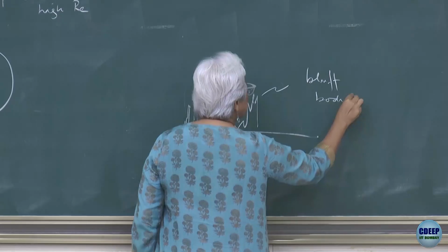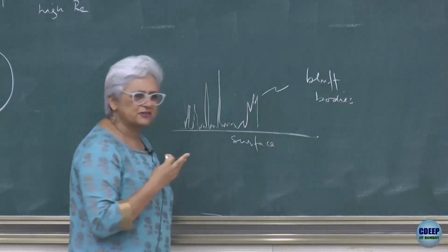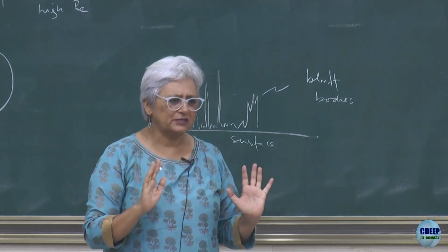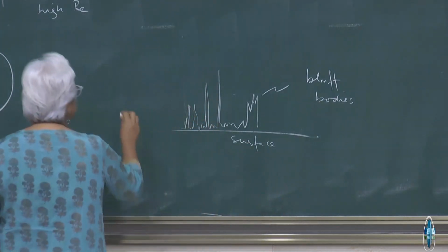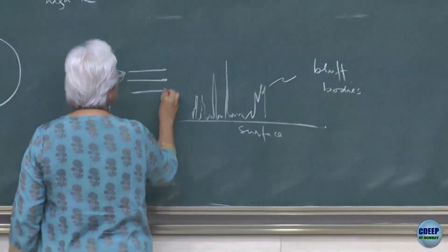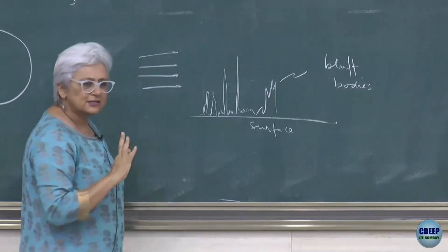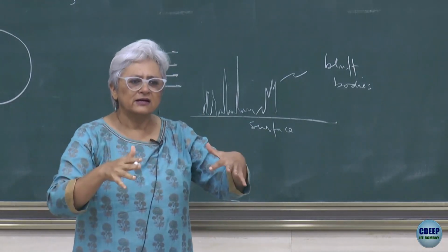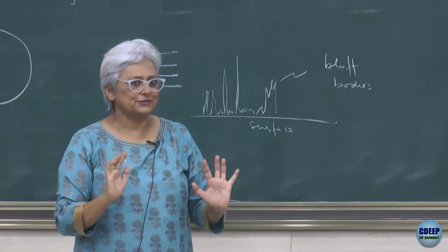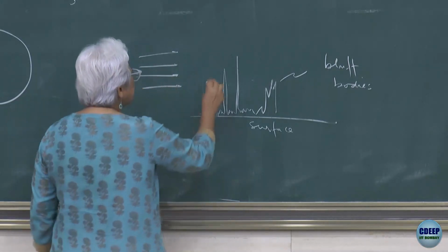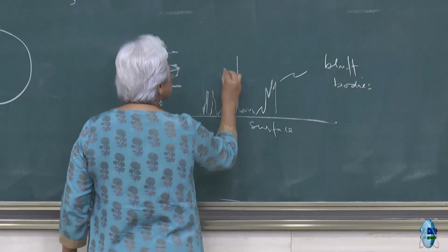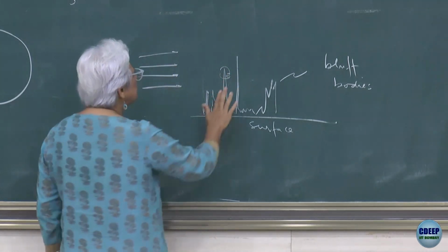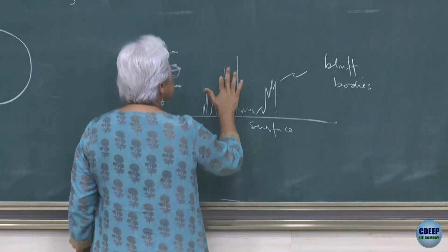By bluff body, we're basically talking about an irregularly shaped body that disturbs the fluid flow in such a way that it causes turbulence, and the fluid separates from the body, and therefore you end up having massive turbulent wakes on the other side and so forth, right. But really you are thinking about the deposition on the front face.